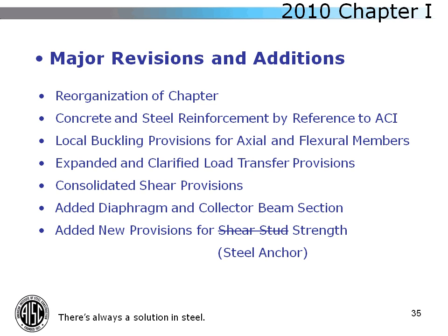This was done to maintain consistency with ACI 318 Appendix D and other documents. You will probably hear me say shear stud about 50 times through the rest of this presentation. Just replace that in your mind with steel anchor and you will be compliant with the 2010 specification.